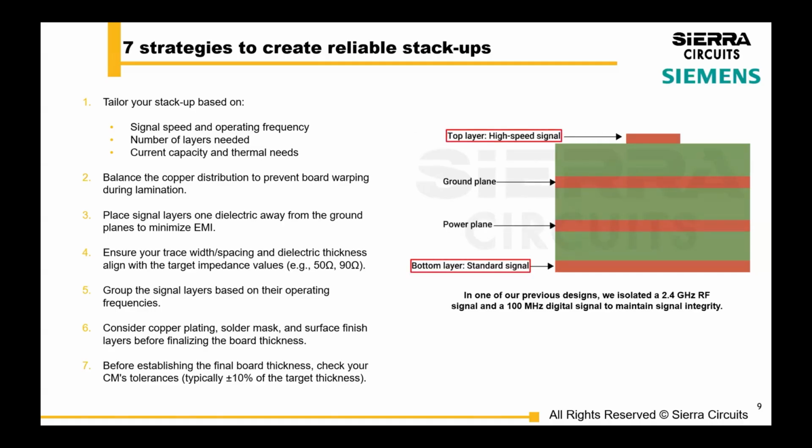I've talked many times in webinars about parallel lines and interesting features like coils. Not every fabricator will flag those as something special to look at, but those features definitely are special, and you should put those into your notes, highlighting them as special. So understanding the topography of each layer, understanding where you're putting your copper pours and whether that'll be able to etch well, that's all important when it goes into the strategy of stack-ups.